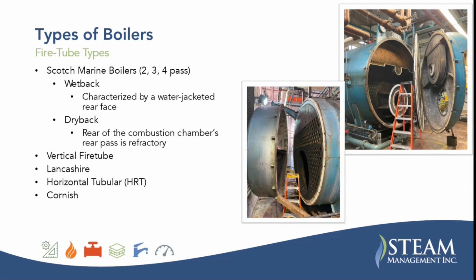heating. When you talk about 2, 3, and 4 pass, that's talking about how many times the flue gas travels across the boiler. So down and back is 2 pass, and then if it goes back across is 3 pass. So that's what that's referring to.